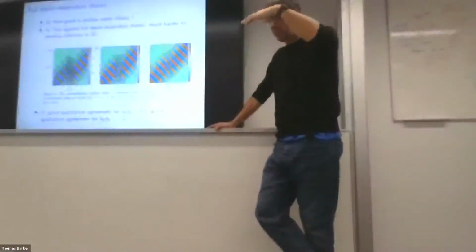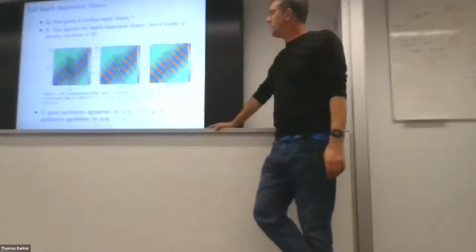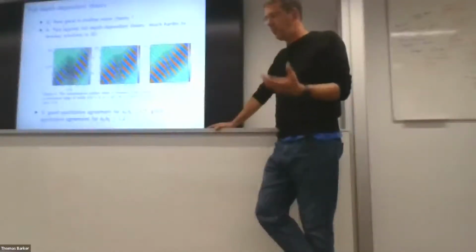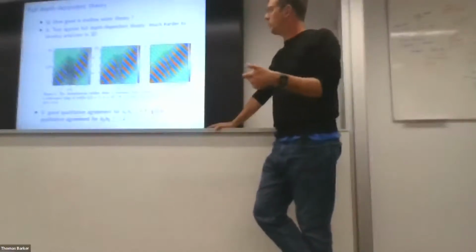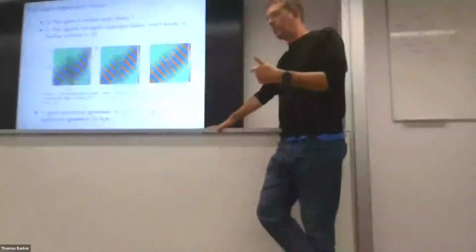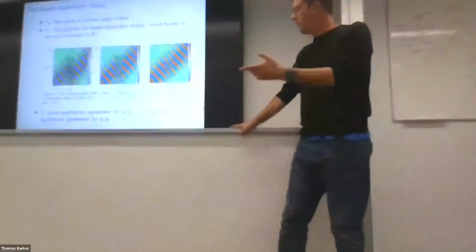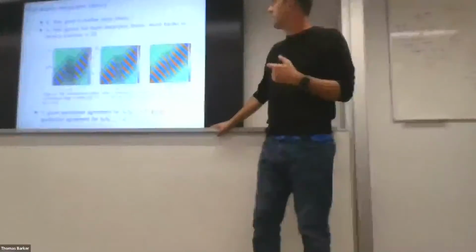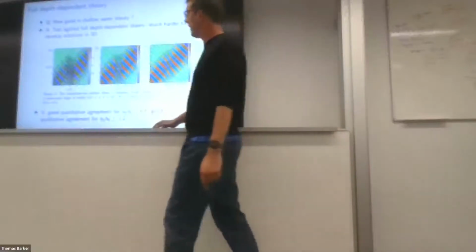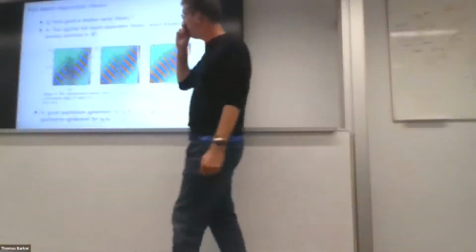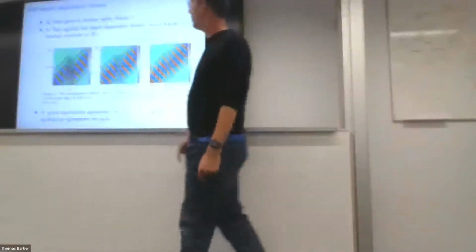That's shallow water theory. So the question is, how good is shallow water theory? It's made upon this assumption that you have very long waves compared to the shallow water. So we've also done calculations using the full three-dimensional potential theory. That's a lot more difficult to solve because you're working with one extra dimension now. But we're able to get both qualitative and quantitative agreement with results. If the wave number is very, very small, that's long waves, then you get very good qualitative agreement, and you still get good quantitative agreement for higher values of the wave number, or for shorter wavelengths. So again, this is just demonstrating pictures like the ones that we've just seen, showing that you can get negative refraction, waves coming in, being refracted backwards and then propagating onwards.